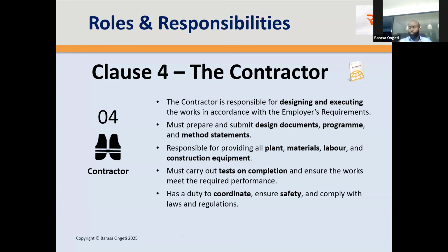I need a road with 2 carriageways, each with a width of 3.5 meters, a traffic island in between, and traffic lights which can function for 24 hours without electricity disruption, and so on and so forth. Those are your requirements. For specifications, you actually specify the material, the equipment, everything that you require for your road. So there's a slight distinction between employer's requirements and employer's specification, okay?